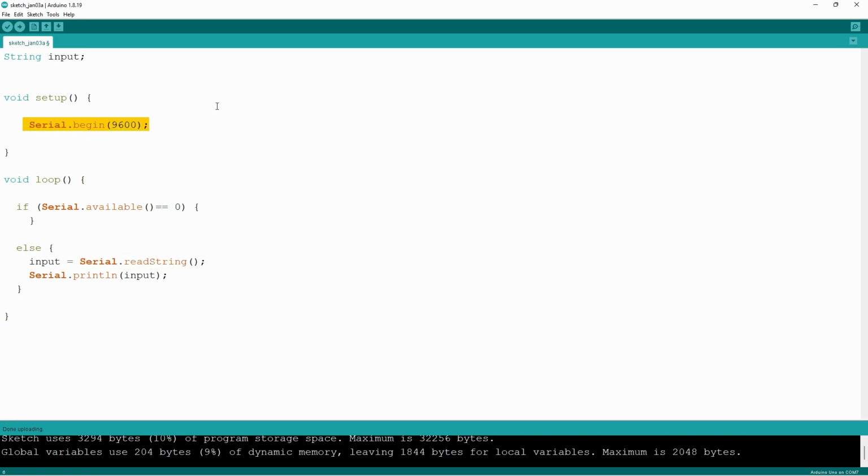Next, I've obviously activated the serial monitor. I've used the same baud rate that the Arduino Uno uses by default. You can also increase and decrease it. However, this is fast enough. The higher the value of baud rate that you include, the faster the transmission of serial data. However, since the data here is very simple, very small, the speed is not really a factor that I'm concerned about. In the void loop, I've used the commands if and else, which I obviously haven't taught and explained yet. I will explain these conditional commands in videos that follow up this one in chapter 2.